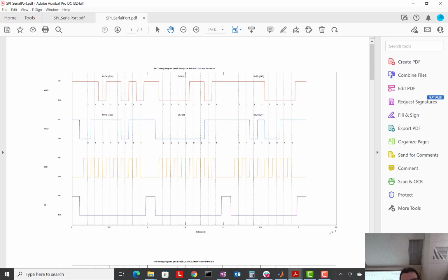I know I'm reading data on the low going edge, so I take that low going edge up to here and see that it's a 1. I've done this for you: that's 1, 1. Go up from here, it's 0, 1. That's how we determine what data is going across the serial port. Write it down and give me the answer in the homework.